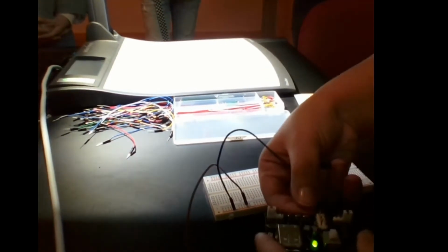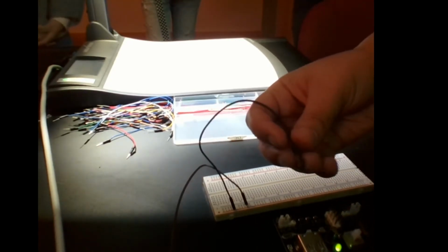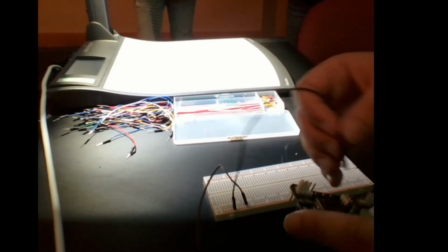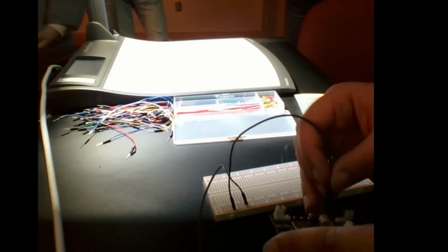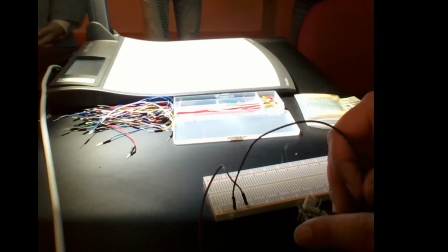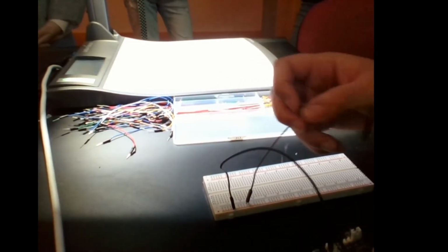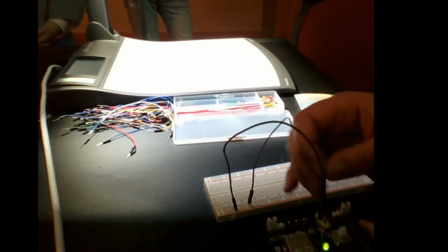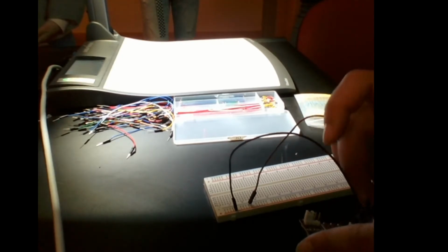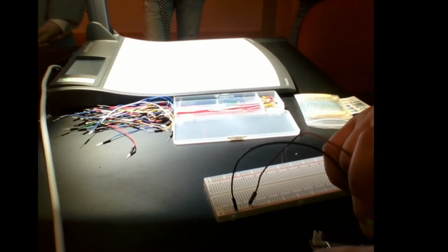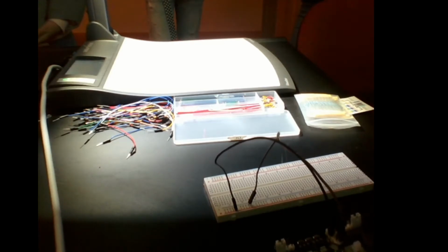But you have ground, so G and D usually stands for ground on these kinds of power supplies. You can see it on the image over there as well. So G and D stands for ground, and usually black refers to ground, so you would plug in your wire to ground, and that is where your reference point is. And then you plug in either 3.3 volts or 5 volts, whichever you need for the circuit. So here I'll be using 5 volts for my demos today. And you can use this for anything.